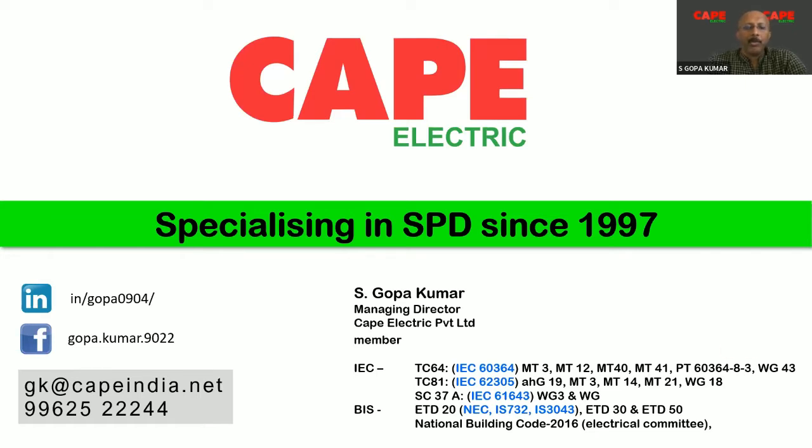Also, SPDs are connected in parallel to the circuit. As a result, in case of any failure in your SPD, the installed site is going to have a problem. So in comparison to other protective devices such as fuses and MCBs, selection of SPD is very critical, because this device is connected in parallel, and number 2, at the end of life this device is going to create a short circuit.